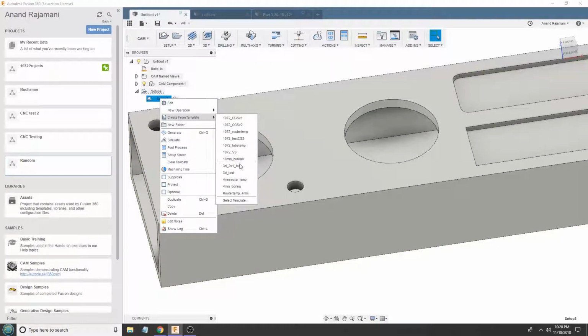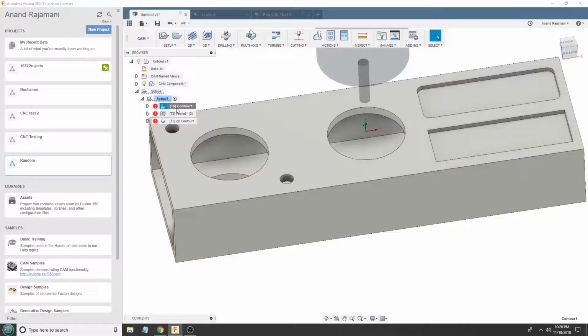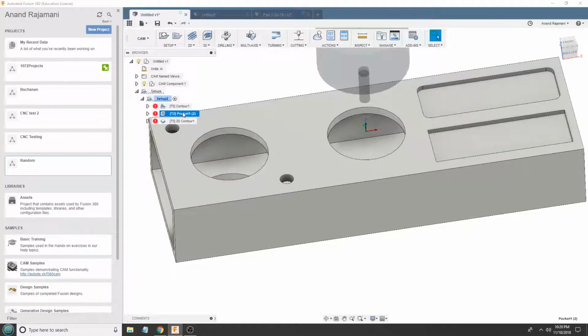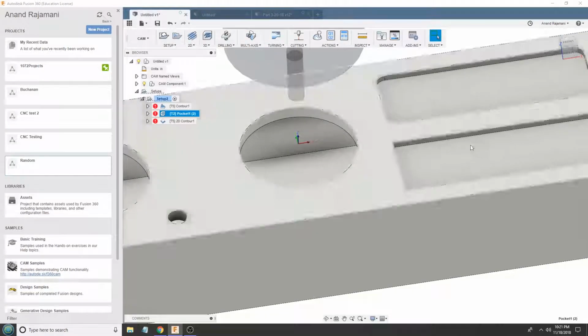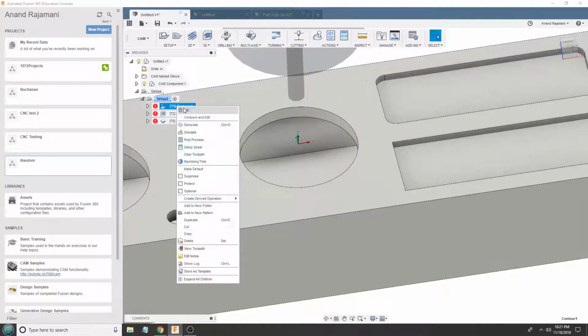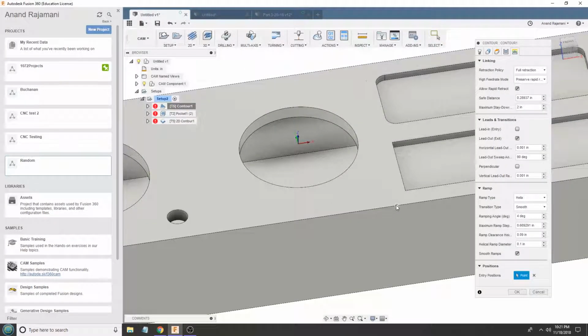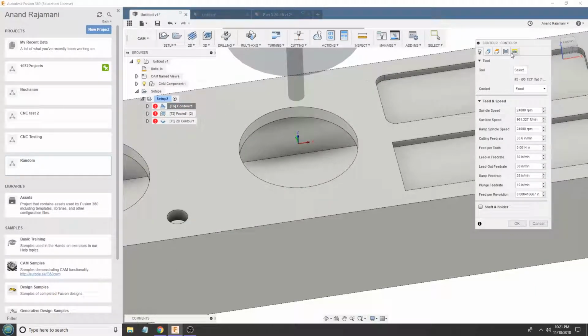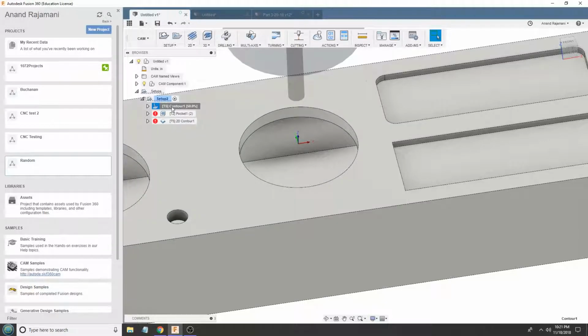Like, no, just nah. We're not doing that. Instead, I've got another template for you guys. 3D 2x1 test. This is interesting because in this one I have a pocket and a contour. The pocket is if you have blind pockets like this one. If you just use contour, which is doable, I select my contour. Or actually, I don't even select my contour. None of that. I just hit edit and then I hit OK. And then it just generates.